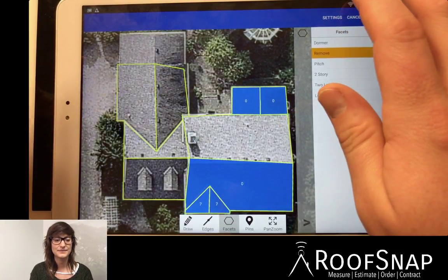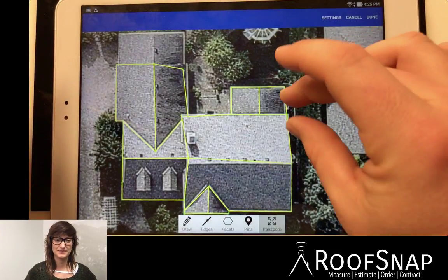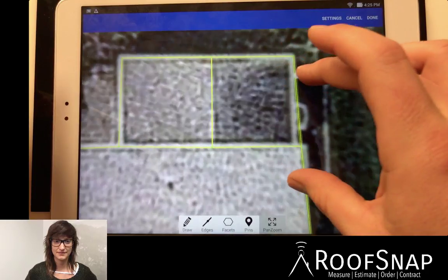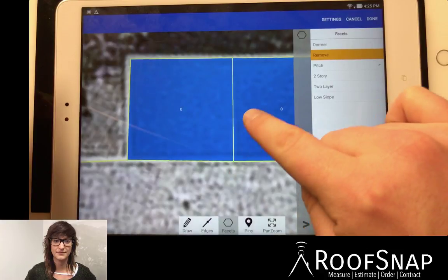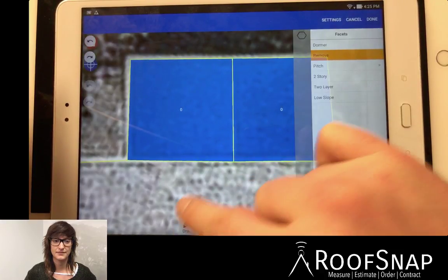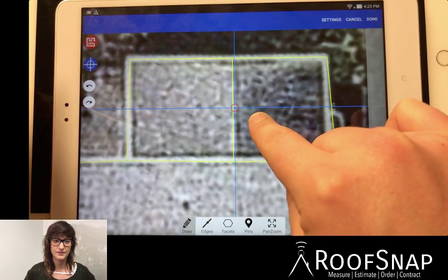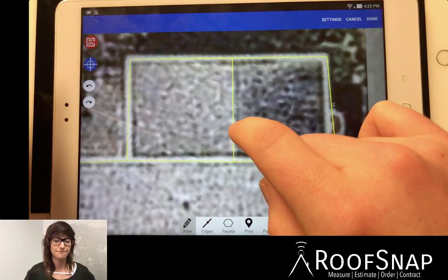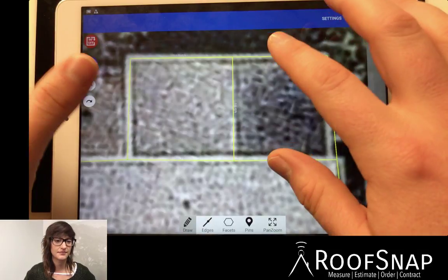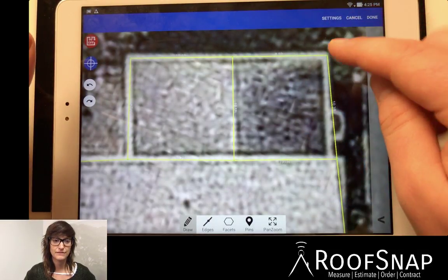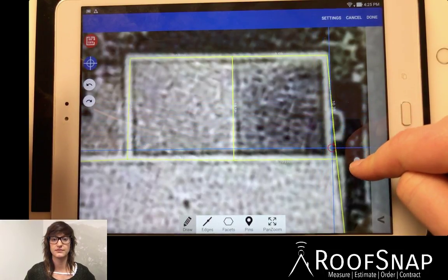And in fact, here we'll find that many things aren't quite right. So let's begin to zoom in and look at one area at a time. To start with, on this rear section, when I go to facets, it looks like this lower, let me turn the facets off a second, this lower roof, these two roof planes here are connected to the eave of an upper roof. There's no step wall coming down either side. This is an inaccurate method for drawing the roof. You don't want to connect. You can even see here that the eave was drawn off and connected at the bottom of a rake of